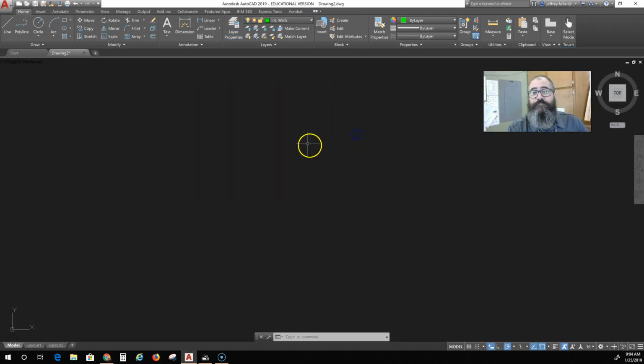But anyway, I'm going to start on layer exterior walls. So I want to go into this little layer panel and click on my exterior walls and be working in that layer. So starting with lines, the way I do it is, I kind of have a shape in mind, and it's hard to get started. You just really have to start somewhere. I think I'm going to start this one over here on the right hand side.